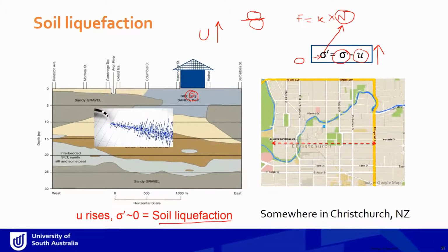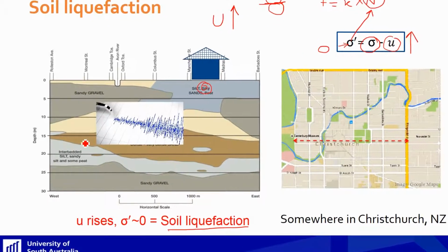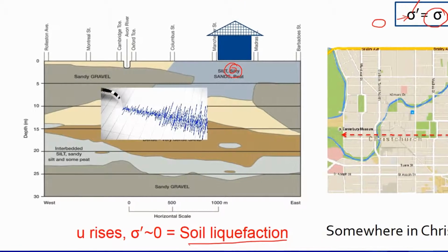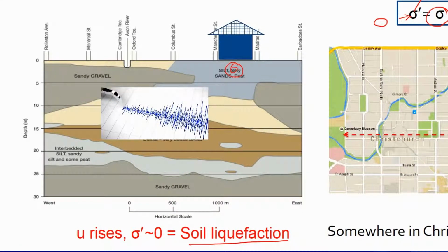Now, it is very common in earthquake-prone areas, in sandy, gravelly soils of this type. It is not that common in clay soil because the pore sizes or void sizes inside clay are very, very small, and it has a lot of cohesion as well, the stickiness between particles, and that prevents it from getting liquefied.